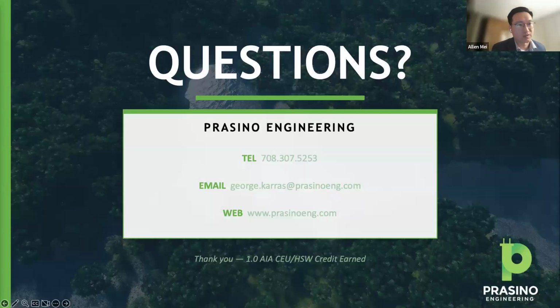That 0.35 is at 75 Pascal of the building enclosure area, right? Basically, that's your air boundary. Generally, 0.4, 0.35 is a very generous number, in my opinion. So that is not like it's a pressurized number, and it's not super stringent. If you look at other parts of the country, like the state of Washington, they made that number, I think it's 0.25 or 0.2-ish. Again, it's not that stringent.